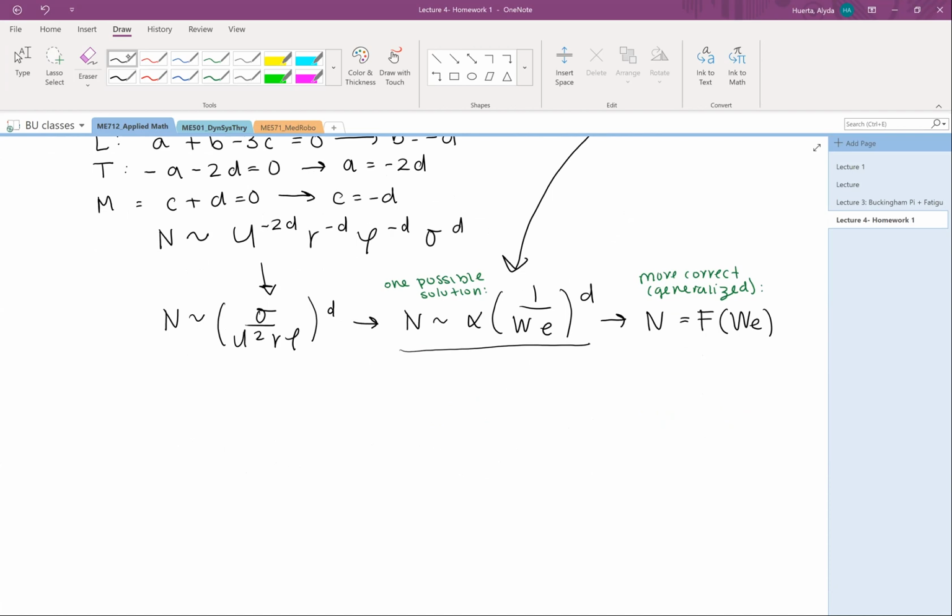In fluid dynamics, for those of you who study fluids, you will know that there are dozens of numbers named after famous people. This is one of them, but they usually represent a dimensionless balance of two important quantities. The Reynolds number balances viscous and inertial terms, and tells you what matters: is viscosity dominating, or are inertia and turbulence effects dominating?